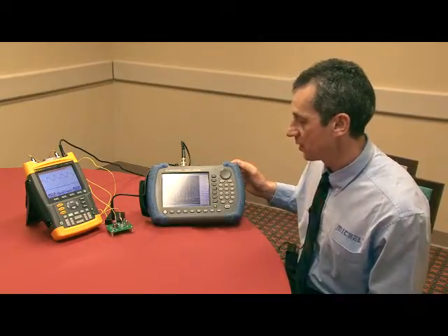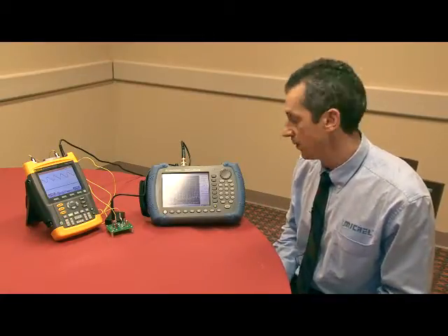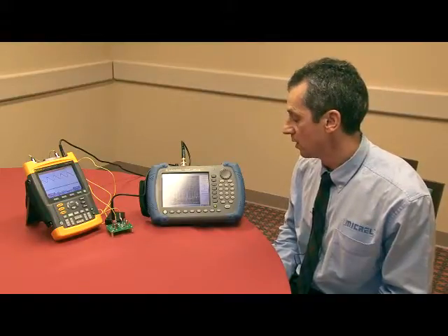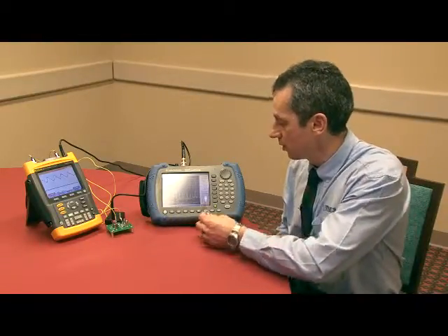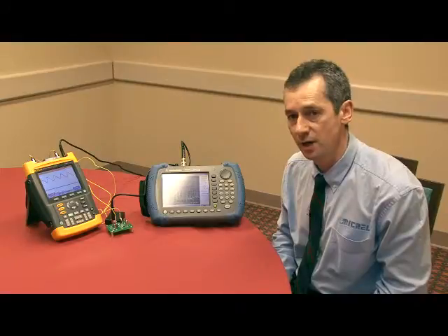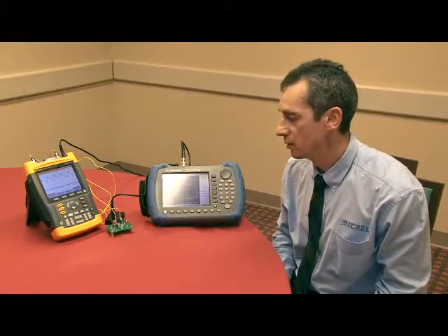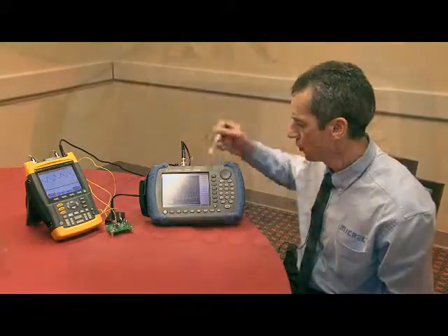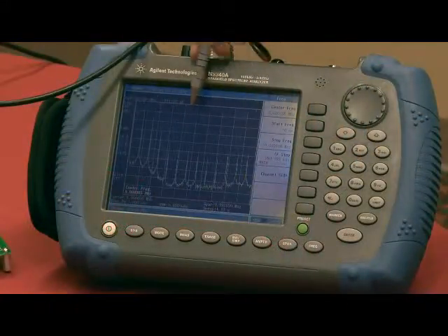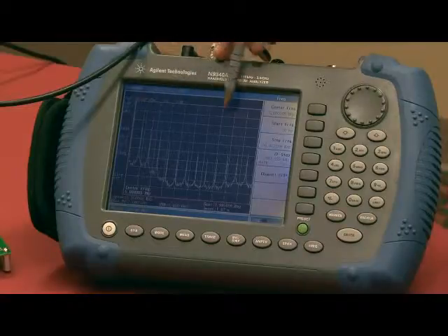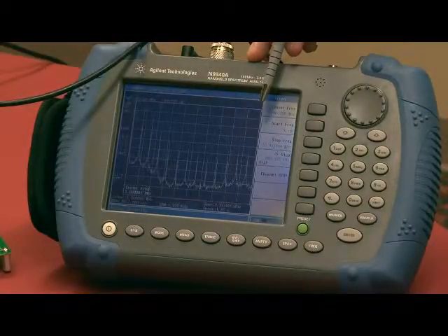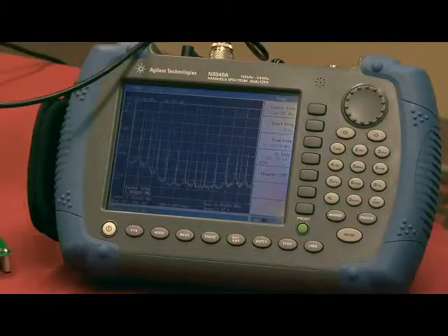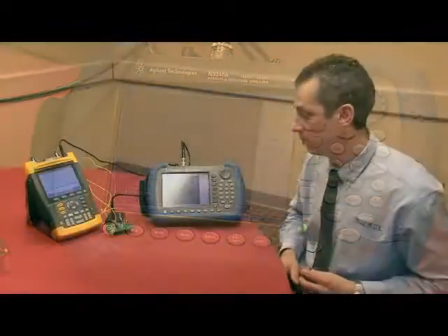Perhaps the best way to look at it is to look at the spectral plot of the before and after the ripple blocker. On the right here we see a plot. Because it's operating at 630 kilohertz in discontinuous mode, the waveform is sawtooth in nature, so it's producing energy content at all of the harmonics. We can see the fundamental here at 630 kilohertz, and the marker up here is minus 20, so the fundamental here is about minus 24 dBm.